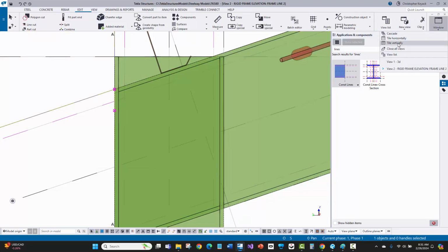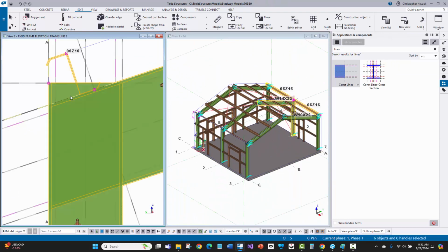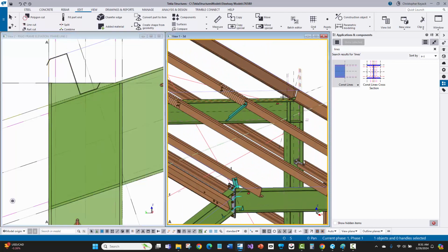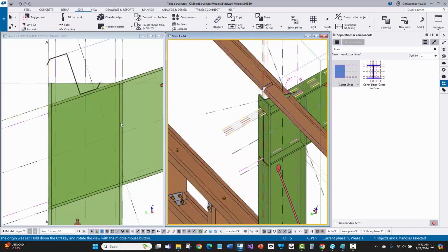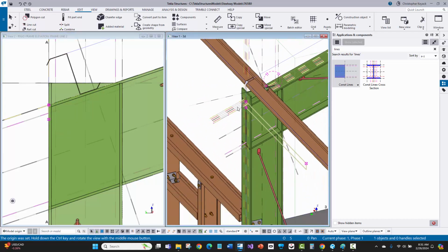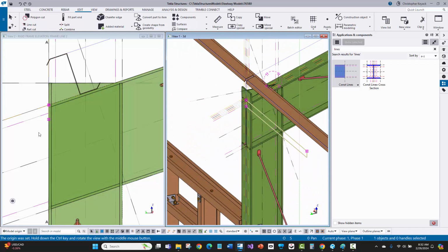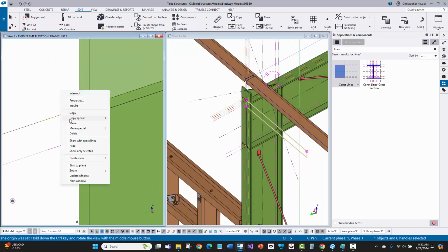Now I'm going to tile my view so I can look in 3D and in 2D at the same time. If I'm trying to figure out which corner or which side I'm at, I'm actually over here. So that's okay. I'll rotate myself around so I can look at that condition there. And what I was showing you is that fitting, right? So there's that large fitting plane, which is that cut, and it cuts that beam all the way across its length there. Now, the thickness of this plate is actually 3/8.